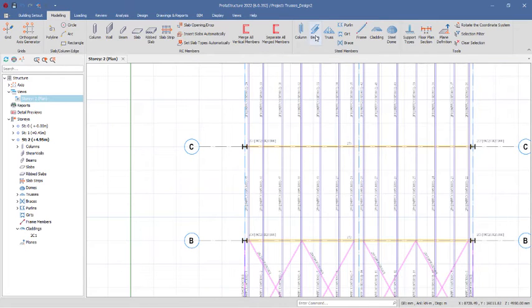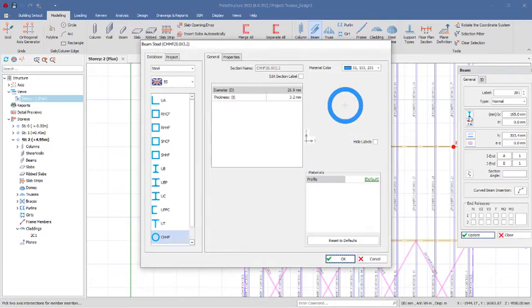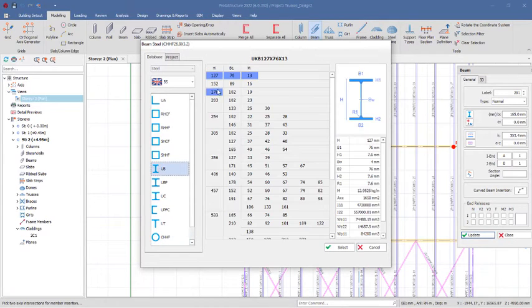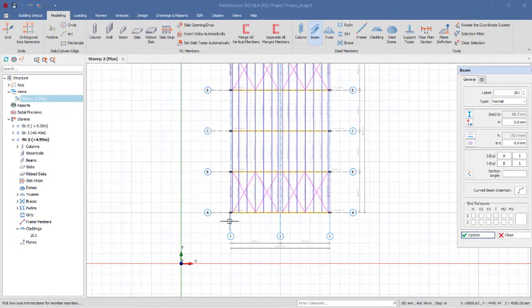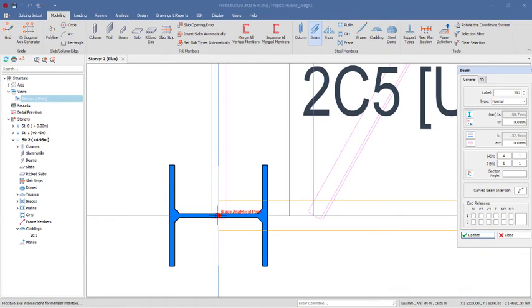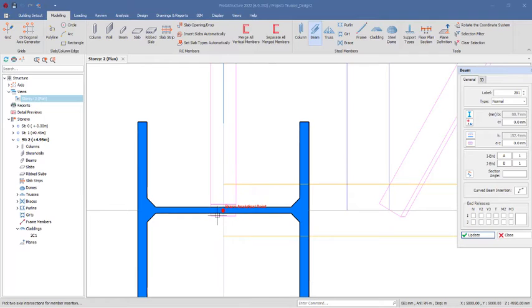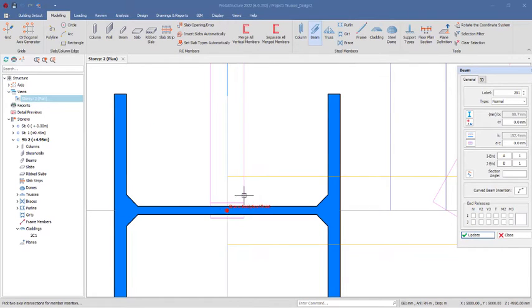So for the beam, we select the steel beam right there, and then in the dialog you just have to choose one of these smaller sections of the universal beam. So we use 150 by 89 by 60, 16 thickness. So click right there and OK. So we have to pick that from one point to another successfully. So we wouldn't want to miss load.